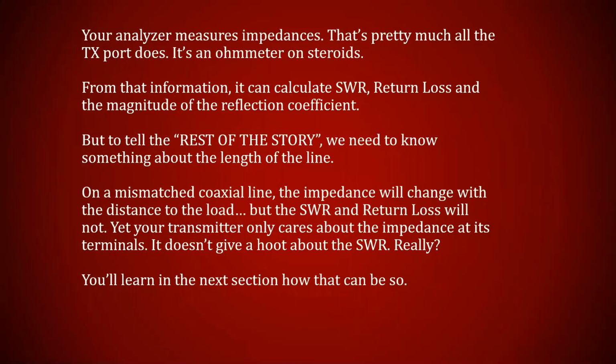So your analyzer measures impedance. It's pretty much what the TX port does. Think of it that way. It's an ohmmeter on steroids. From the input impedance, it can calculate SWR, return loss, the magnitude of the reflection coefficient. But in order to tell the rest of the story, we do need to know something about the length of the line.